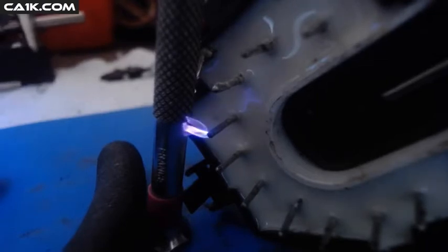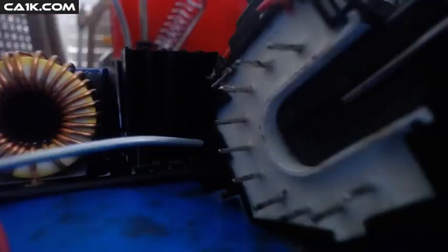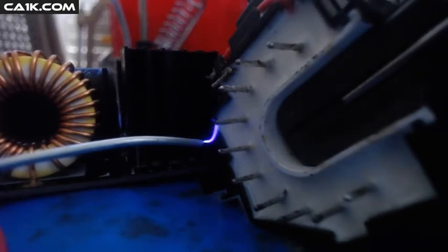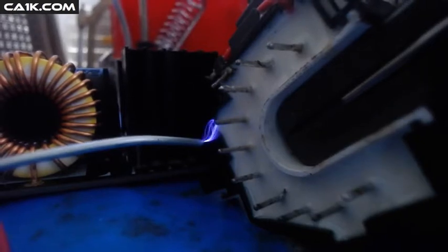Before we begin, I must let you know that I'm using a flyback transformer to supply the primary Tesla coil circuit with high voltage. Now, at the time I did these tests, my flyback transformer ran on a lithium 9-volt battery, so that's why it stops after a few seconds. If you want to power your flyback driver for an extended period of time, don't use a 9 volt. Also, you'll drain the battery's power very quickly since the driver draws a lot of current.